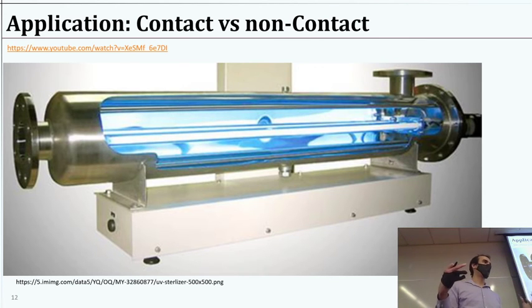The quartz sleeve is fragile, the lamp is fragile, and it has mercury in it. So we want to be careful with both of those. That quartz sleeve gets a little bit hot given that it's got the light source right next to it. It's going to get dirty. It's going to accumulate stuff. It also tends to be negatively charged, so it's going to accumulate junk on it. You have to clean it. You're probably going to have to scrape it, and you're going to want to be careful when you do that, because it's expensive, because it's this fancy quartz, and it's fragile. So it's not a great situation.